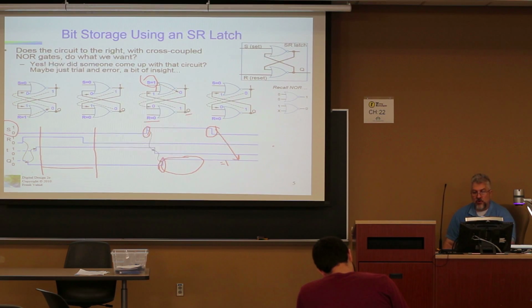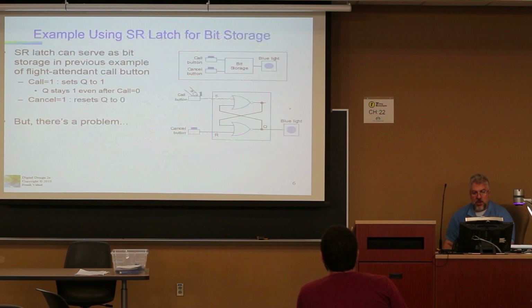Now, how do I unstore it? Well, let's take a look at this example again. Remember, we press the call button. Call button becomes 1, and the R input over here is a 0. So we're using this SR latch to light up this blue light. But, oh yeah, cancel equals 1. So that means, oh, by the way, we're holding it down too, right?